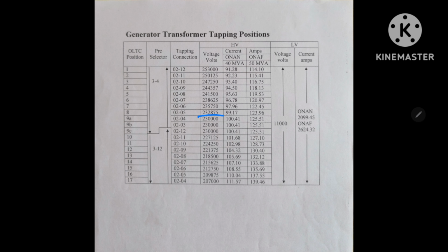So this is the nominal voltage. And here step by step we are adding. That means when the primary voltage is rising, we are adding step by step, plus this is 100%, 1.25%, 1 plus 1.25%, plus 1.25%, like that we are adding. In the same way, minus 1.25%, minus 1.25%, like that the final will be 110%. Here it will be 90%.